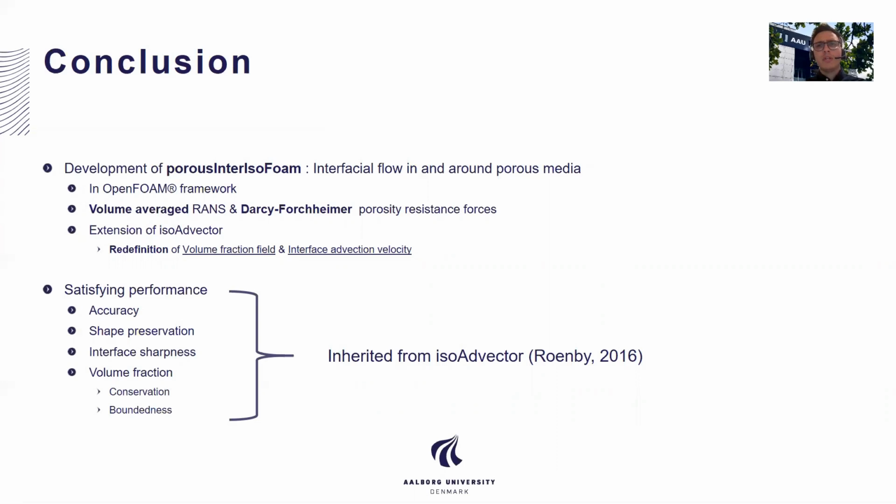Apart from the governing equations adjustment, isoAdvector also had to be extended by the redefinition of the volume fraction fields and the interface advection velocity. The benchmark cases gave a clear outcome with satisfying performance in terms of accuracy, shape preservation, interface sharpness, and volume fraction conservation and boundedness, which are apparently properties inherited from the best interface advection algorithm, which is isoAdvector.